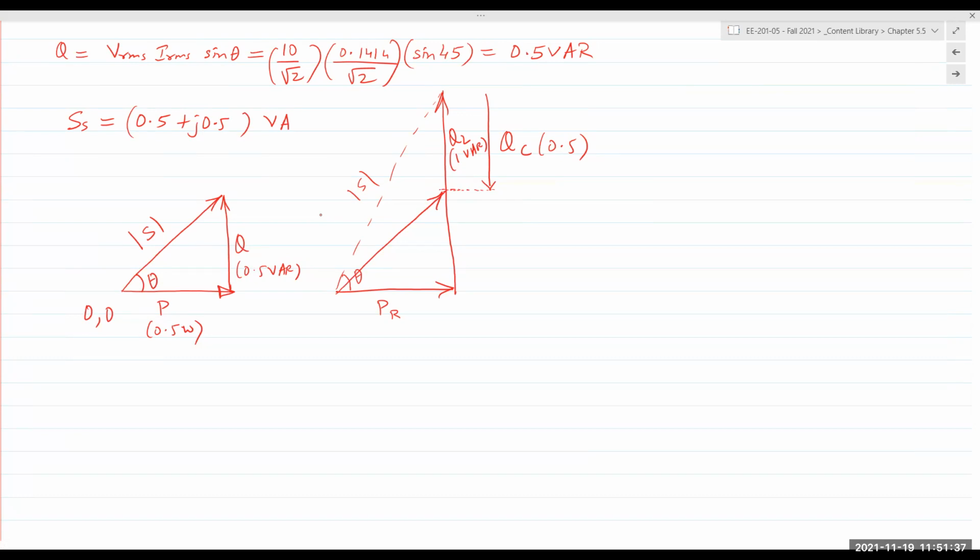Ideally, the highest, largest value of the power factor would be 100%, meaning I do not require any reactive power at all. If I do not require any reactive power, then the angle is 0, and cos of 0 is 1, or 100%. As the angle gets larger, the power factor decreases. So 0.9, 0.8, 0.7, so 90%, 80%, 70%, and so on.